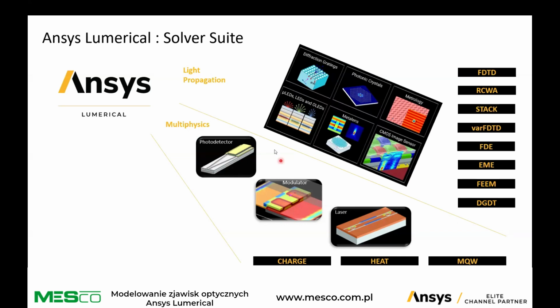So when you talk about a photodetector, you typically need an input like a light. So we can model the light propagation in the photodetector, and light will propagate here, for instance, in this waveguide and in this taper, and then it will be absorbed in the active material. In this case, it could be germanium, for instance. And the absorption of light in that material can then be used as a charge source in the charge transport solver.